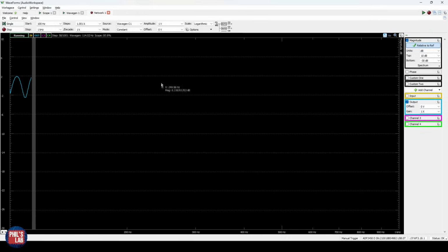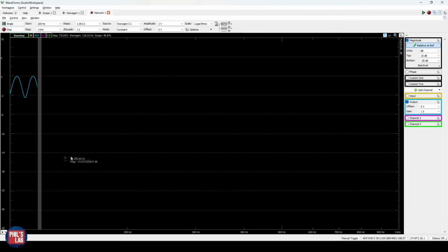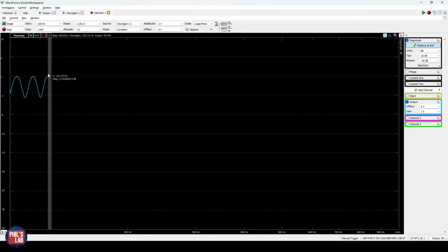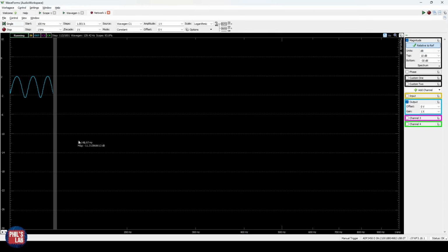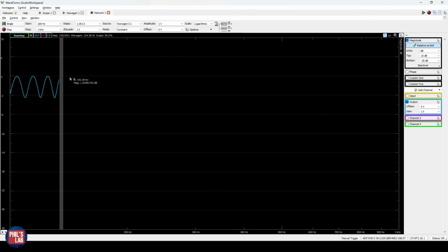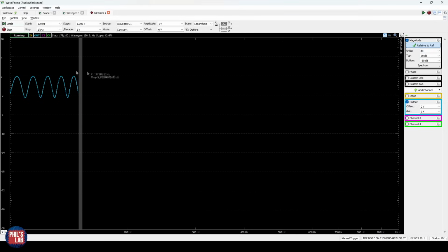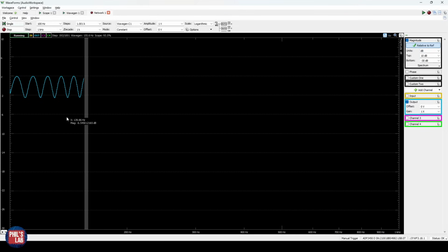The frequency response is then of course also altered. We don't get this special case with alpha equals beta equals 0.5. This is alpha is 0.8 and beta is 0.2. And we get this rather different frequency response still with this comb-like behavior, where we get far less intense minima. So let's see what this sounds like with the guitar.